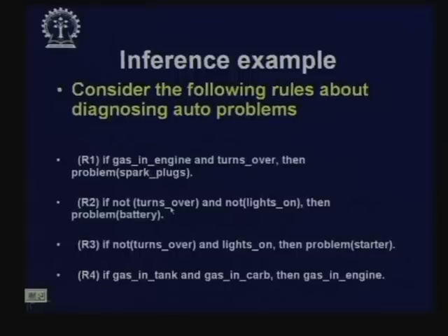If as you turn the key it is not turning over, so that initial sound is not coming, and the lights are also not on, then the problem is with battery. If it does not turn over and the lights are on, then the problem is with the starter. The fourth rule says, if there is gas, meaning petrol, in tank and gas in carburetor, then there is gas in engine.